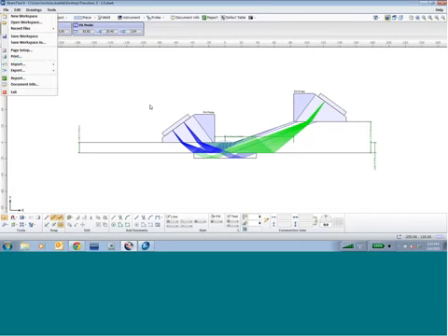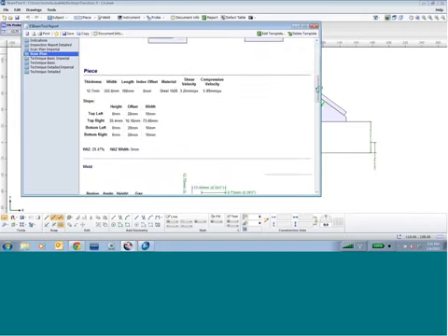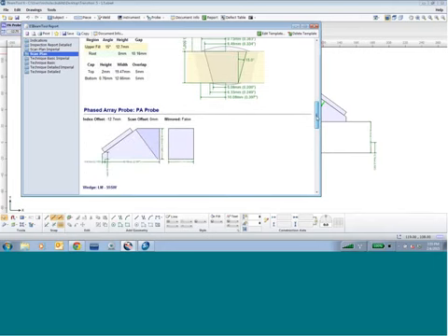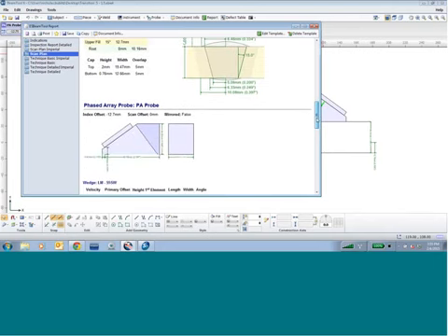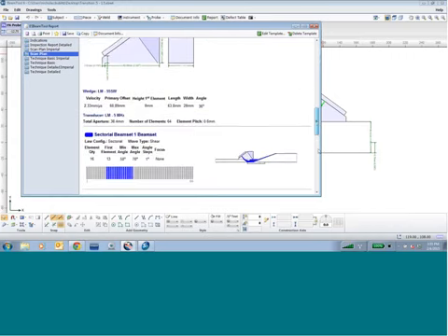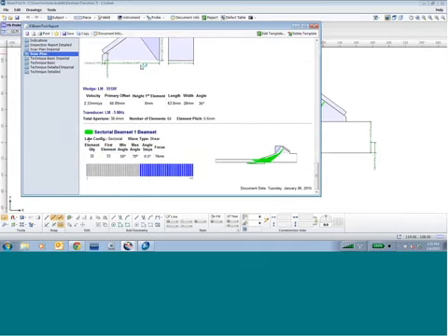These programs allow you to take these scan plans and transition them into a report format that you can then show either the client or the inspector, and give them the step-by-step instructions on what you were testing, what you were using to test, and how you actually put together the beams, the elements, and the position of the transducer in order to do the inspection. So this gives you a good layout for how that scan plan was implemented. And that's always an interesting step in the process.